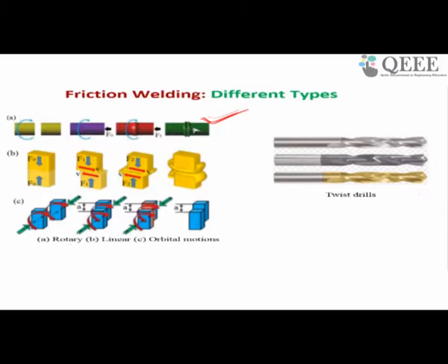You applied friction to soften, meaning to induce heat at the interface. So friction welding is a simultaneous application of heat and deformation. Heat was given because of friction between two mating surfaces. Then deformation was given because you gave compressive force, so that joining happened. So this one class is called rotary welding.